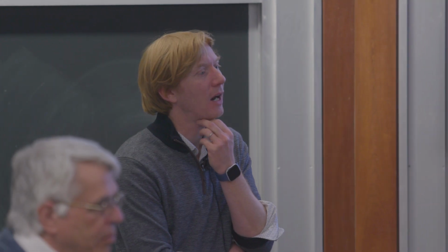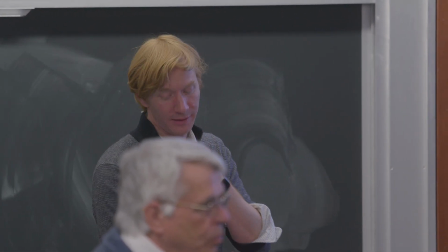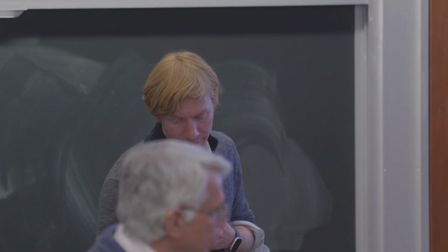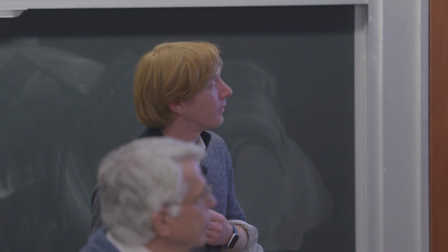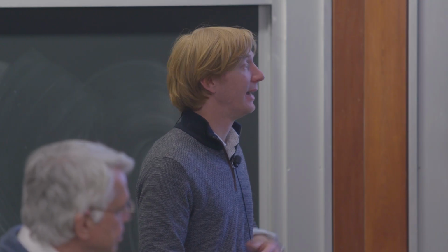Yeah, we could. Our description of the boundary is essentially this: on the boundary when we apply the PDE, we have a set of disconnected points with normal vectors. That's all we need to even do fourth order elasticity. And so by design, there's no topology or connectivity between these points at this stage.